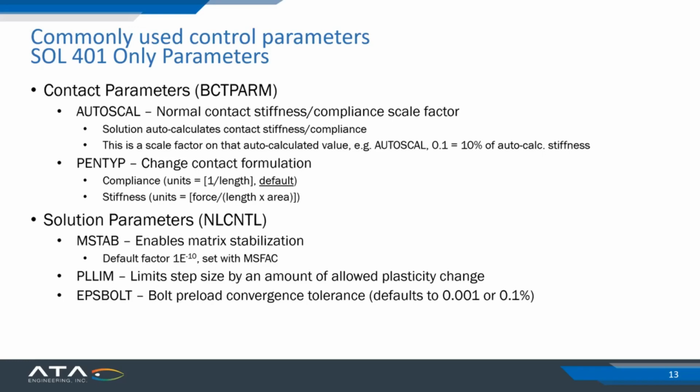But generally speaking, bolt preloads, when you're torquing them down, you're going to have 25% uncertainty in that preload based on torque. So it's a little strict, and it can cause the solver to iterate a lot unnecessarily. I usually set it to like 1%, because it can iterate a little bit to get to 1% and then a lot more to get to that 0.1%, and 1% is usually good enough.